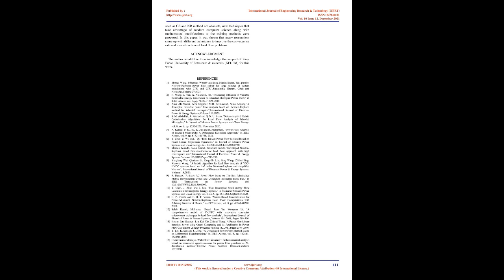Numerical analysis based on successive approximation for PF problems in AC distribution systems [15]. This technique is basically a modification of the conventional Gauss-Seidel method using successive approximation, which does not require derivatives. Instead, it requires matrix inversion, which is used throughout the remaining iterations. This method can handle both mesh and radial configurations of AC distribution systems.